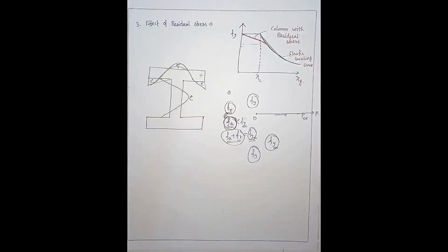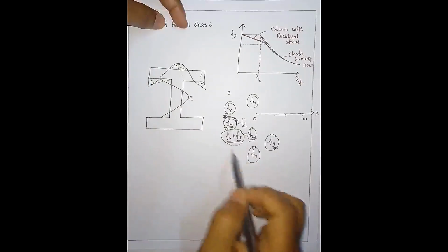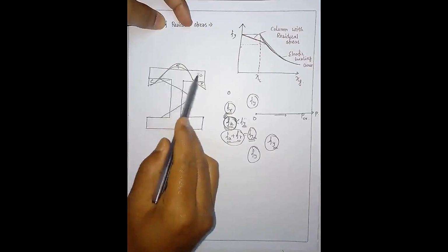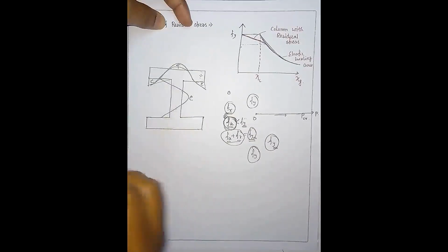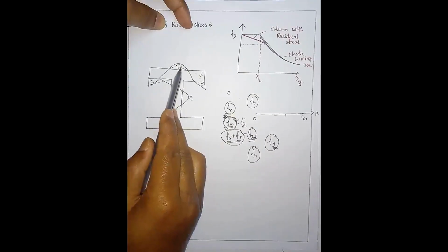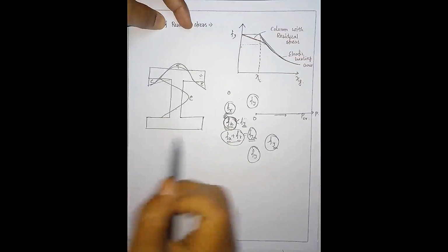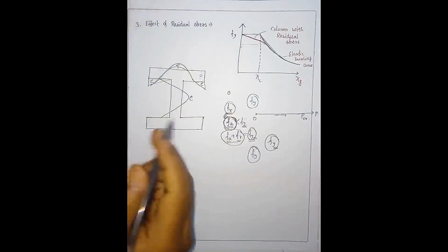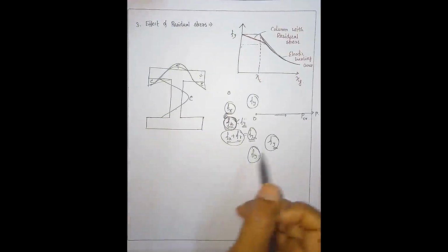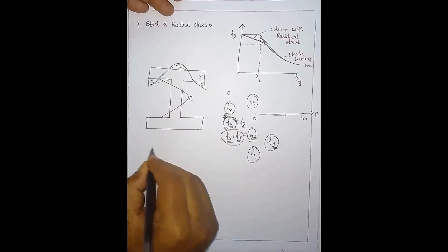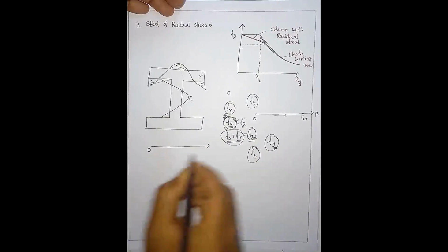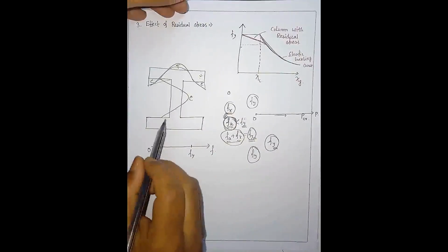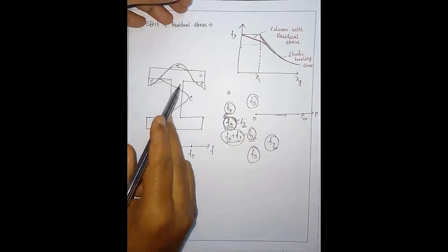Okay, so let me brief this once again. Some part will be under compression in any cross section, and some part will be under tension. When we apply compression on these ready-made cross sections, where some residual stresses are already present, we are increasing the stress. So, zero stress, and suppose this is Fy and this is F.